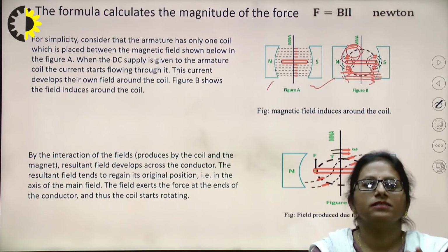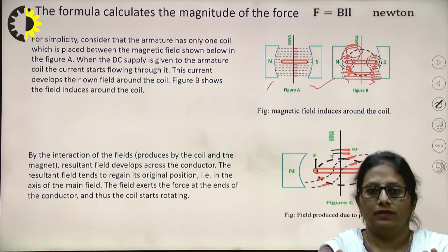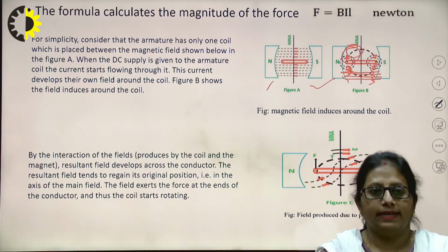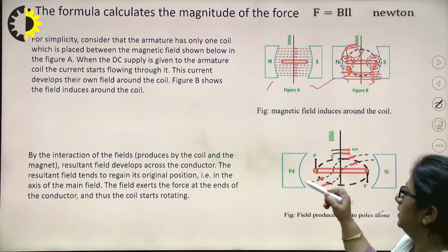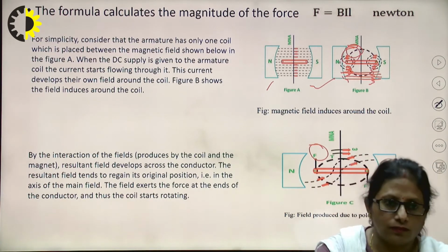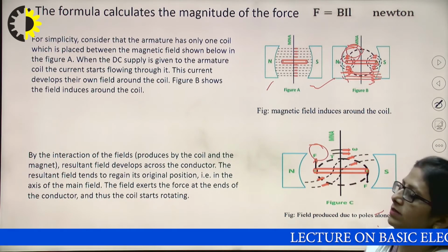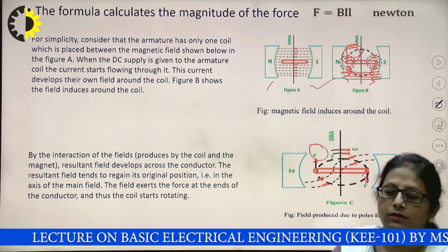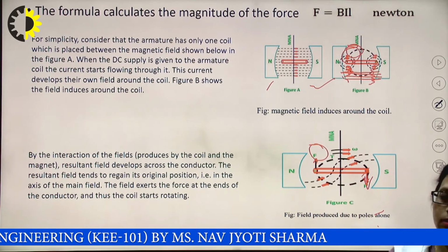So this acts like a stretched rubber band, you know. If you stretch it over towards your side, the paper you have will be pushed towards the lower force side. The same thing happens with the conductor as well. So I have the maximum flux being created over here, and on this side I have a minimum amount of flux at this area. So the force would be exerted towards this side, towards the conductor. The same thing happens for the conductor over here. This is the cross convention, so this time it feels the force in the downward direction.